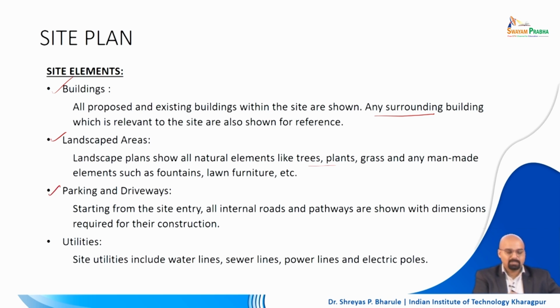Next, you have all the driveways and parking ways, parking locations. For the driveways particularly, there will be different types of dimensions. Wherever the width of the driveway changes, at all those locations you have to mention the dimension as well.